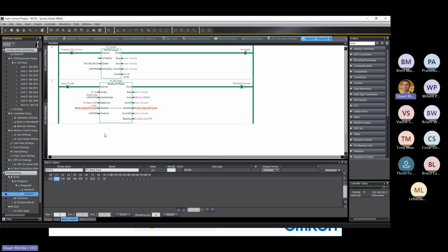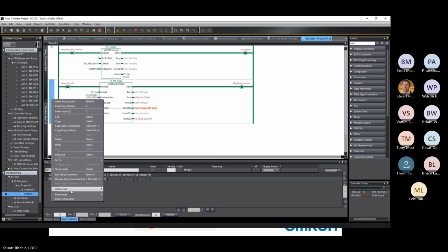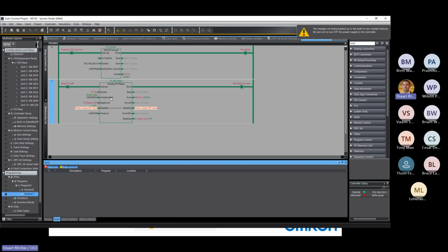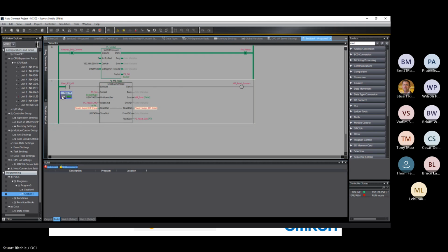It's going to be a Modbus connection, but we'll try that, because if that works, then it parses out the data automatically for us. Okay, yeah. It looks like we do need to parse out the data afterward, but if you remember the trick we used for assigning the same address to two variables, that would work just fine for this. It is one additional step, but Modbus is a bit cumbersome to begin with.